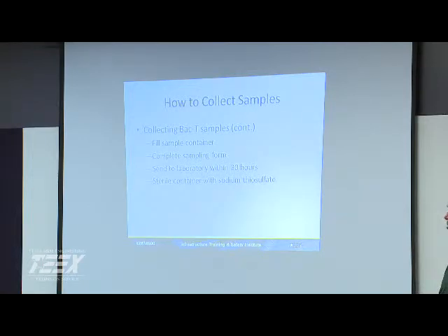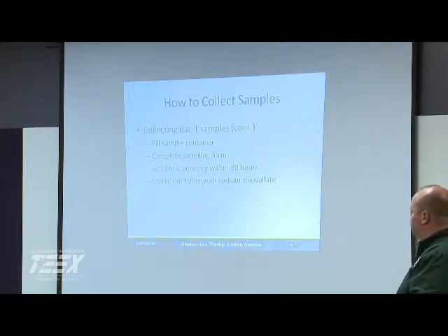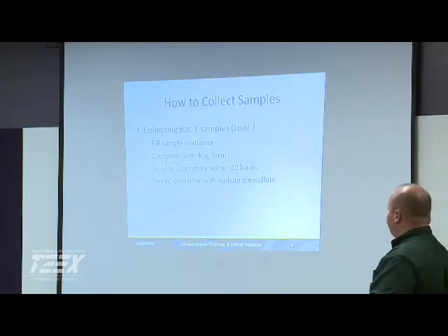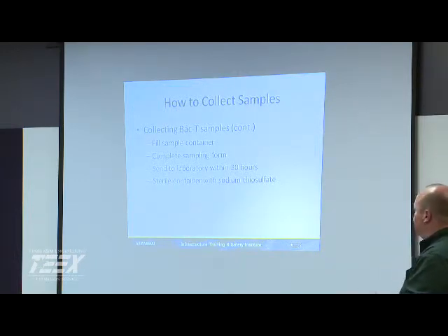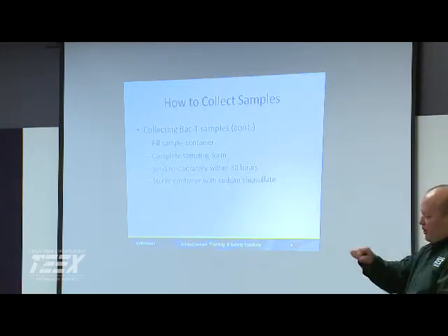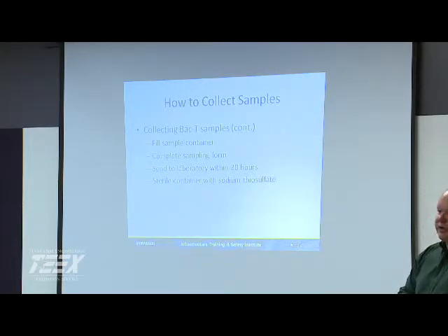Okay. Within 30 hours: a 6-hour hold time on microbials, and then a 24-hour transit time that they give you in case you have to ship it off somewhere. So 30 hours, really the test should be run at that point. You have to have a sterilized container. Sometimes people add their own sodium thiosulfate. It's so easy to get it with the tablet in there now. You just don't have to worry about it.